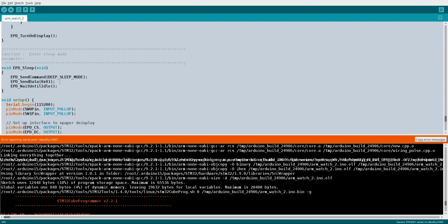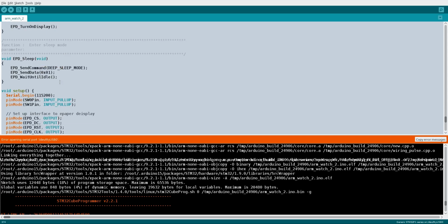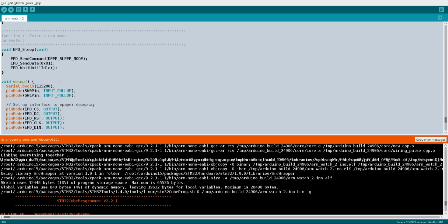There's a sleep, so that puts the display in deep sleep mode, so we'll be using that. That'll be useful. Cut down on the amount of power used, so I'm hoping to put the display into deep sleep mode and then the processor into a sleep mode, go to sleep for quite a long period of time. I'm not sure how long, 5 minutes, at least a minute. So the display will only update once a minute at most, I think. Maybe 10 minutes, maybe 15. I mean, you could go into a very long mode where you just update very occasionally, but anyway, that's later. Depends how much power is used for an update, really, and the battery life that is needed.